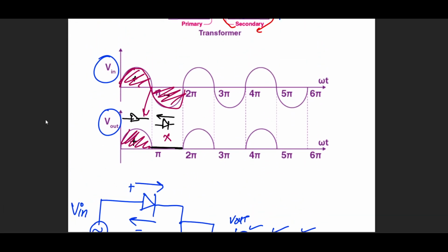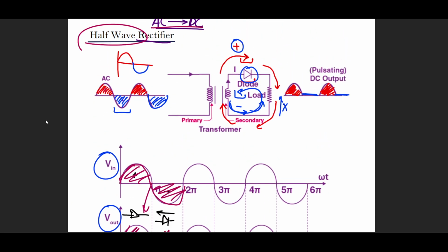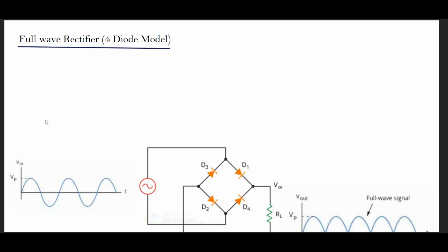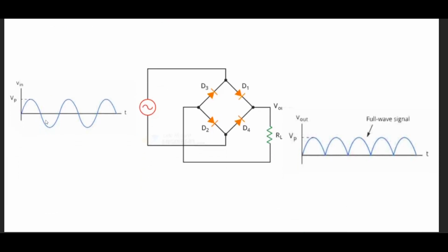And your mobile phone chargers, your laptop chargers, your UPS even also employ this technique to convert the AC electricity to DC output, so that this can be stored in the batteries, because a battery is a DC source. Although not a half-wave rectifier, we use the full-wave rectifier. So let's see how the full-wave bridge rectifier actually works.